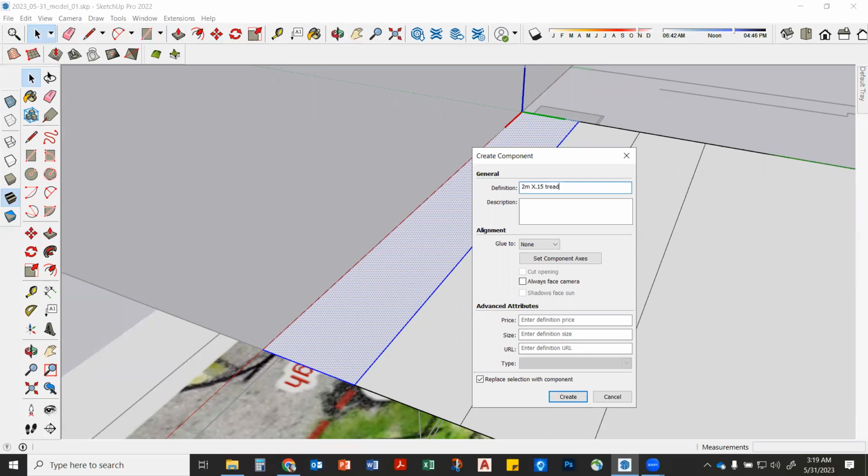You guys know what a tread and a riser is? Yes. Thumbs up. Tread and riser. Awesome. How wide's a tread? 30 centimeters, approximately, right? That's what I do when I'm designing first. But as I'm getting more detailed and going into construction documents, I might change that. It might only be 150, and it might be a wider tread than 300. Maybe I'll go to 400 to make it feel a little more relaxed. So 300 mm for the tread, 150 mm for our risers. Okay, so we're going to create this.